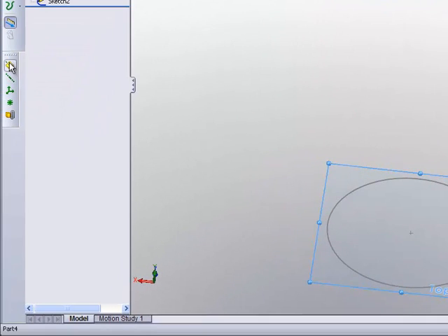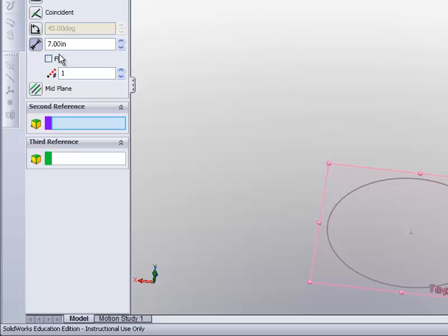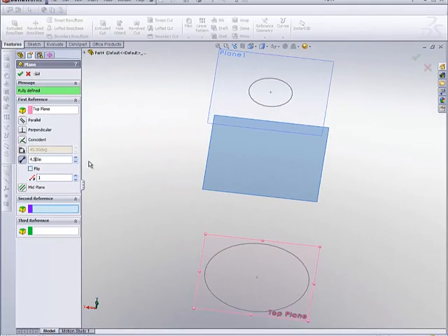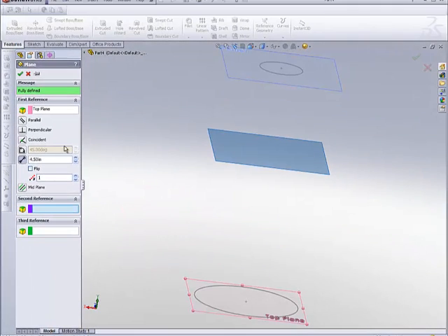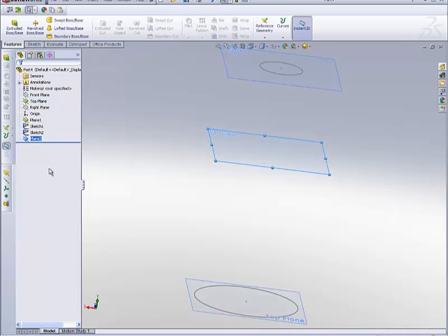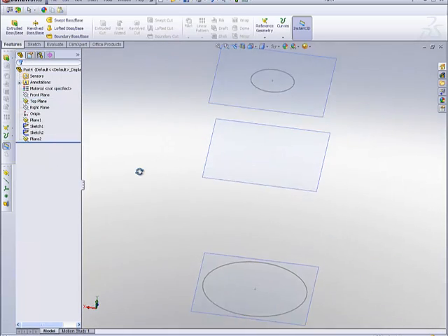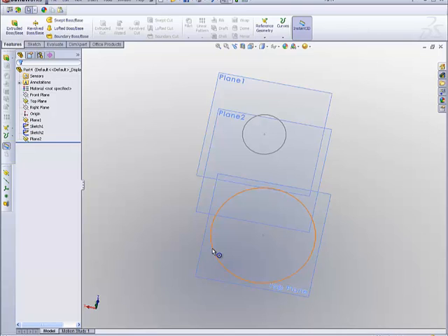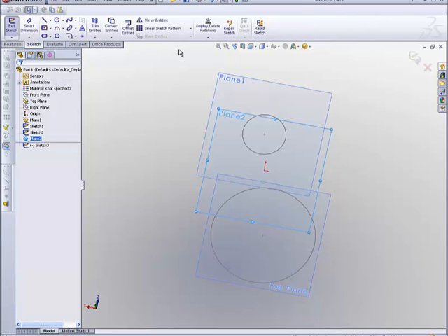So select the top plane, go plane, and we'll set this one at 4.5. It's sort of a nice mid-range. So now this is 3 inches, this is 1.2. We'll set this one then to right around 2 inches.